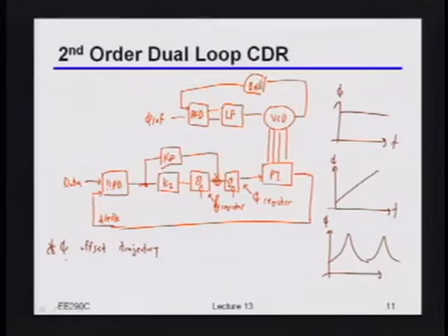Among the choices of techniques are things like adjusting the divide ratio dynamically, and in fact usually using some fractional-N PLL for that. There are some similar examples that we'll walk through in a second, where let's say you had a phase interpolator at your output, and then instead of tying it into a feedback loop, you had some deterministic trajectory you created through that phase interpolator. But basically pretty much anything that mucks around with the PLL, you can use to create really weird looking trajectories, especially if you know what it is that you want to do. Not to say that it's an easy thing to do, but there are lots of different ways that can potentially be done. Okay?